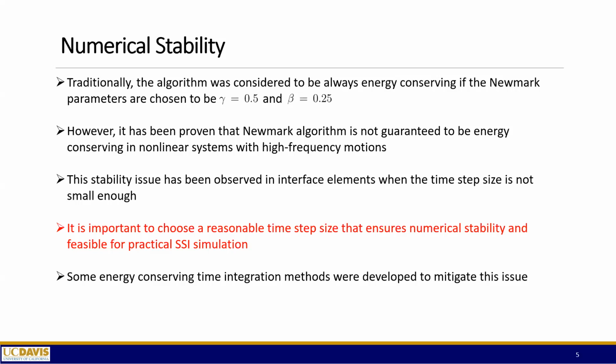So this stability issue has been observed specifically for the case of soil-structure interaction. Remember we talked about the interface elements. When the time step size is not small enough, there could be numerical stability issues. So it is very important to choose a reasonable time step that ensures numerical stability. However, when we run a really large SSI simulation, we also need the time step to be feasible, because we cannot have too many time steps, otherwise the simulation will never finish.